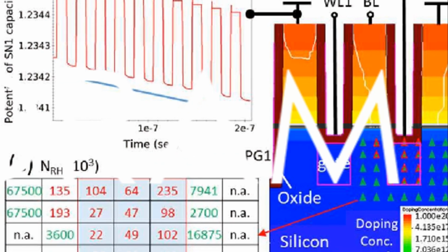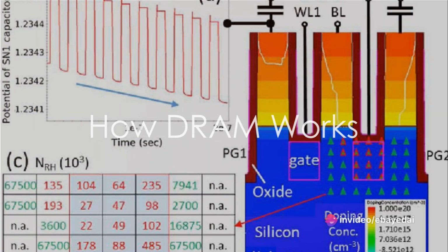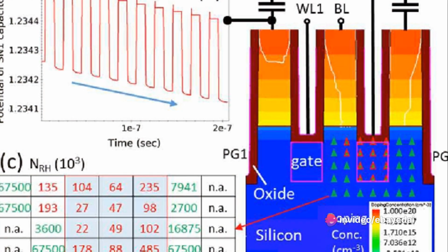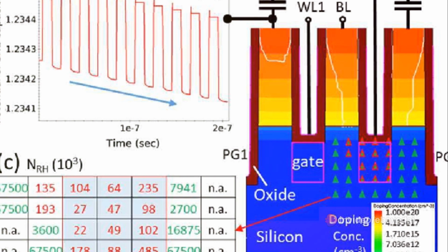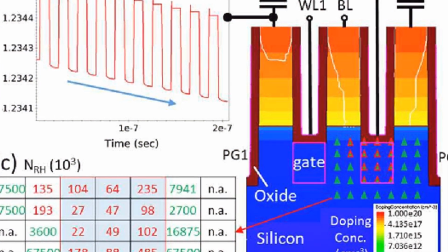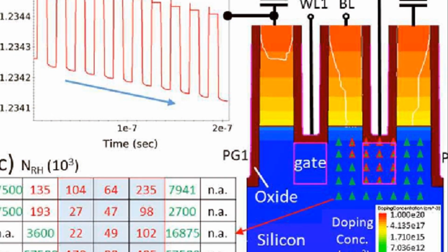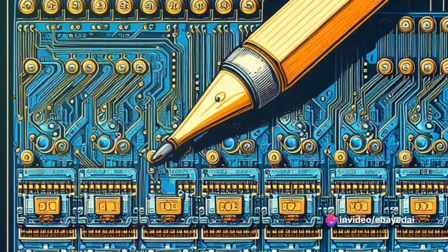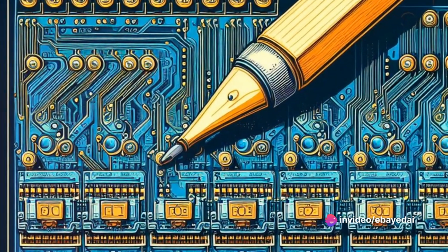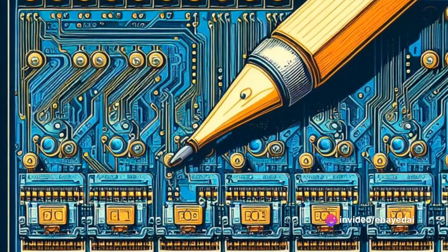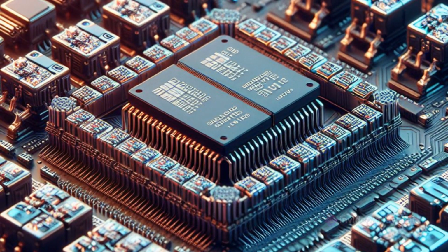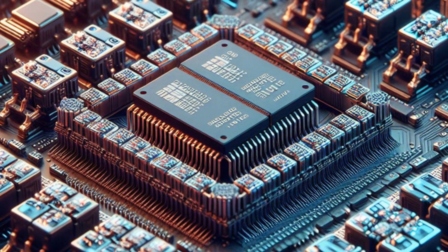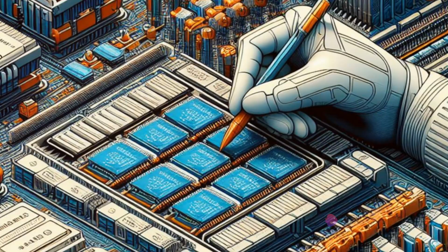In dynamic RAM, DRAM, each bit of stored data occupies a separate memory cell that is electrically implemented with one capacitor and one transistor. The charge state of a capacitor, charged or discharged, is what determines whether a DRAM cell stores a 1 or a 0 as a binary value. Huge numbers of DRAM memory cells are packed into integrated circuits, together with some additional logic that organizes the cells for the purposes of reading, writing, and refreshing the data.